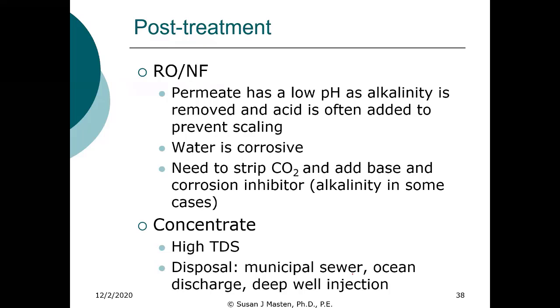And finally, the water that you're producing, especially if you're using reverse osmosis or nanofiltration, is essentially devoid of minerals. I showed you the images from the pipes in some of the residence halls. Once that water has passed through the RO, there are essentially no minerals in it. It will typically have a low pH, as the alkalinity is also removed. The water is highly corrosive. So typically what you need to do is add a base.